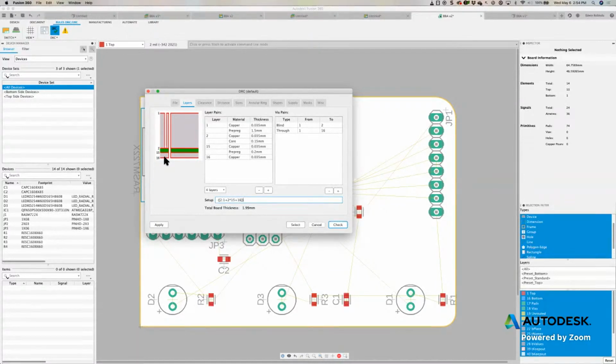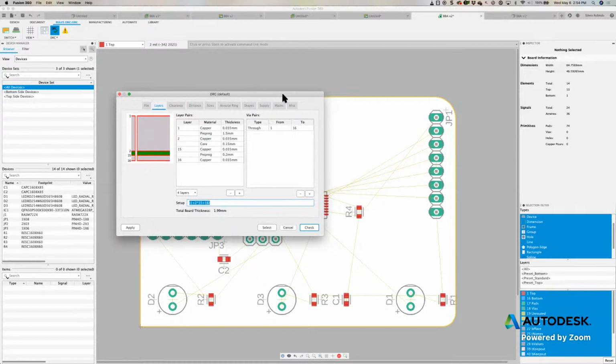It works really well, but just to let you know, it's going to quadruple the price of getting your boards made. It's just a heads up. So you want to kind of stay away from that if possible. If you're making a cell phone, 6 layers, and it has to be really tiny, of course you have to use it, but just take into consideration, it is going to be costly.